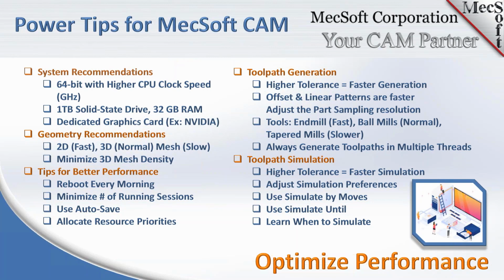If you're scanning something, typically users crank the accuracy on the scanner as high as it'll go, and then you'll end up with 5 million facets in this mesh that you have to cut, which is not good, because it'll take too long to calculate, and you can actually run your system into an infinite loop of calculation if the mesh is too dense. But we have a module for that. We have a mesh module if you want to get into mesh modeling and how to work with your meshes and get them more pliable to use with CAM.